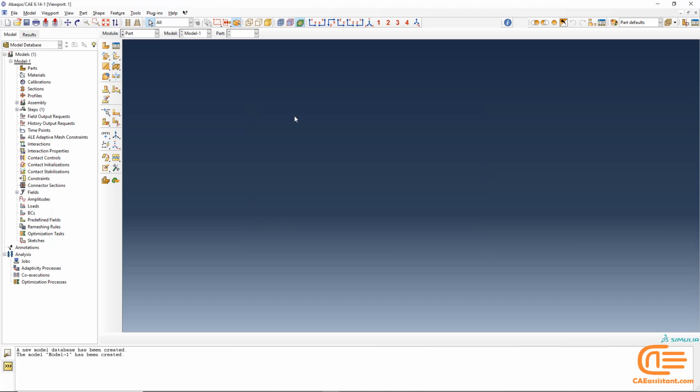When you select a database, the home screen will look like this to you. Abaqus is divided into functional units called modules. Each module contains only those tools that are relevant to a specific portion of the modeling task. The appearance of the window changes as you work through the modeling process by moving between modules. So you are being guided toward completing the model in consecutive windows, where you're user-friendly, and in each window you define a bunch of problem features and work on one aspect of your model. These classifications are done in such a way that they can be repeated for each simulation problem. This is a great feature of Abaqus.